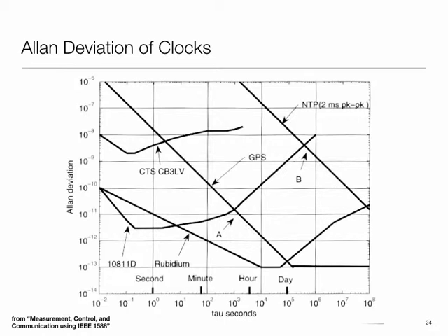And what you start seeing is that it has a very interesting stability characteristic. Over a very long duration, it again begins to suffer issues. But otherwise, it shows some very interesting characteristics. This one, I think, is just a regular crystal oscillator. So anyway, different clocks, you can examine the Allan variance, and then you can look at what time scale of stability you are interested in and work with that.